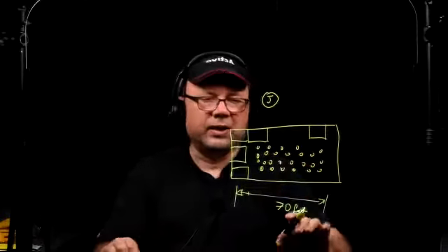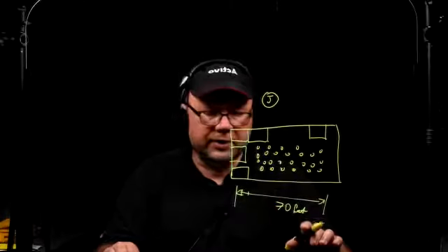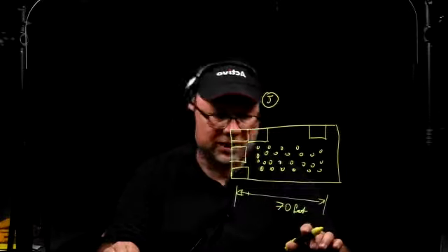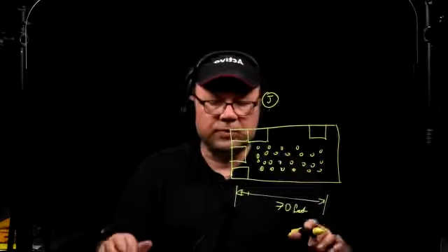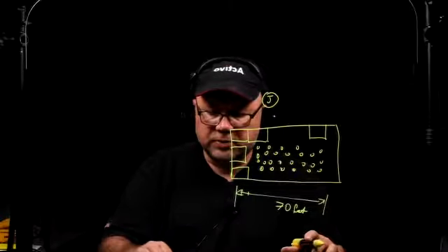So you're going to have a bunch of circles with the J, J, J, J. That's going to be the J hooks, and you're going to use the highlighter to distinguish between the data and everything else, which in our case is the PA system. You're going to use different highlighters for different sets. That is supposed to help whoever is installing it to take a quick look at what cables they need to install and where, so there's no trouble as far as the logistics of the wire installation. This is just to make the efficiency as high as can be.